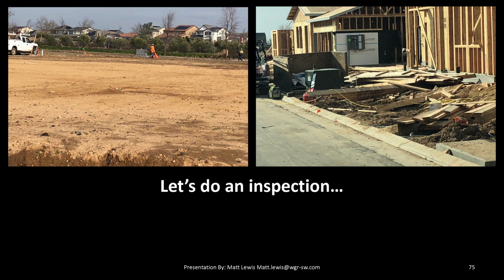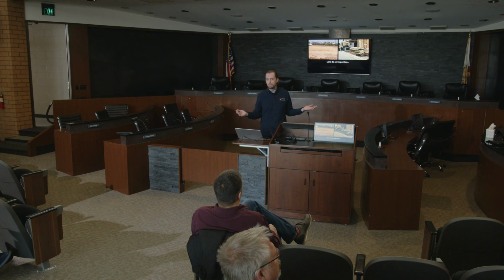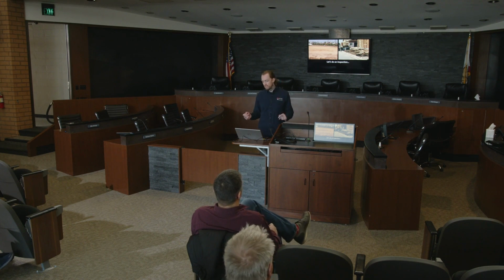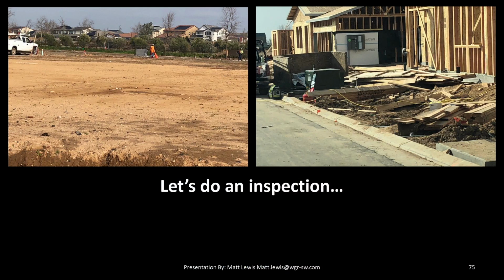And then they have their construction material, which looks like a lot of wood, but they had bags of spent concrete. They had nails all over the place, which are going to rust in a rainstorm. And it just looks like a general disaster. And you can kind of see that sediment is starting to peek out over their curb cut back. This is one of my sites that always prefers to have a curb cut back, but they don't always stay on top of it.